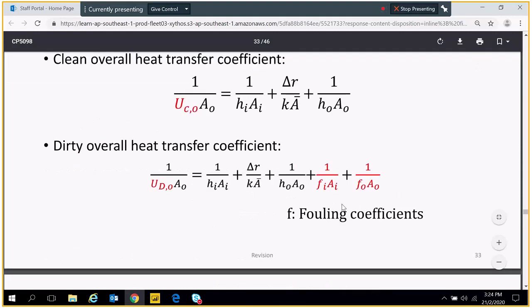But this is best done using Aspen, because when you have internal fouling, in the shell side or the tube side, you can use Aspen. Now, when there's fouling in the actual equipment, you can read the inlet temperature and outlet temperature for the shell side and the tube side. Based on the temperature alone, you can use Aspen to figure out whether any fouling occurs inside the heat exchanger. But that subject is for you to look into when you go to year 3.